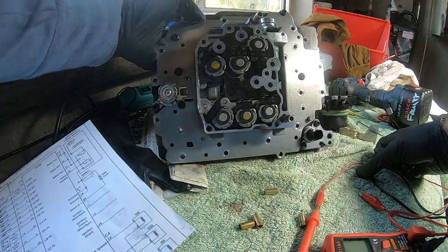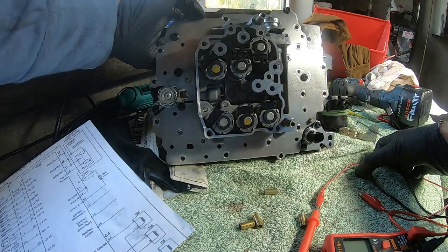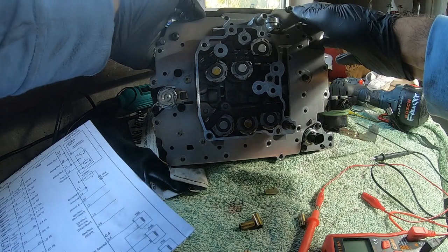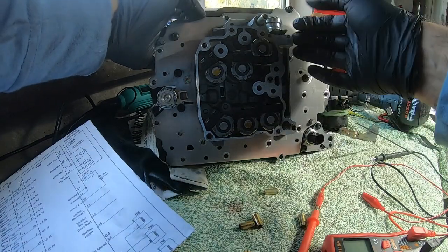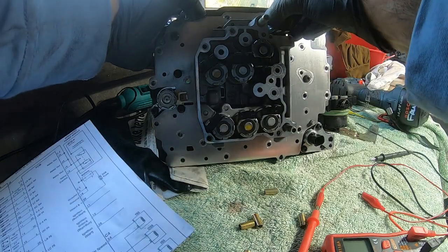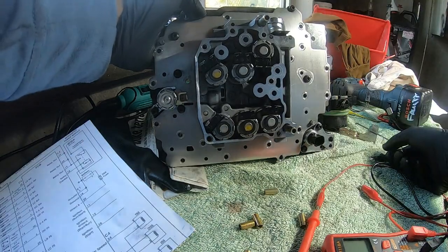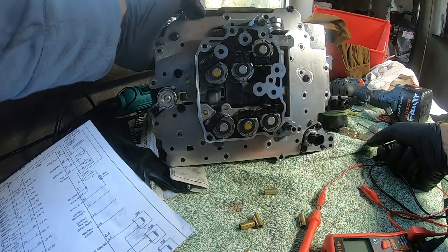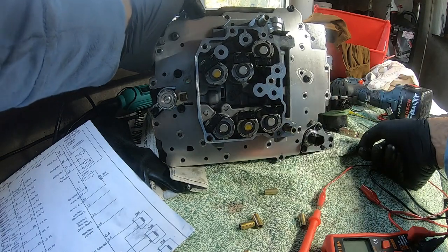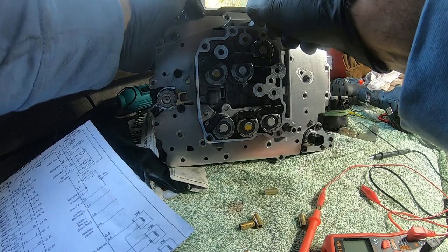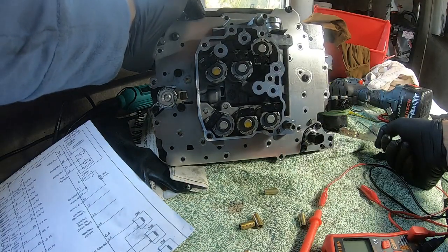You can take them out, clean them, measure their resistance, and then put them back. To take this one out, you'll have to take out the whole valve body, remove this whole setup, and at the back there are these 2 pins which are holding it down. You have to push these pins out, and only after that it will come out. I usually never have any problem with this one, and the reason I'm working with the transmission, it does not have anything to do with whatever I'm doing right now. So I'll just ignore it because it was working fine already. These 2 dowels are permanently mounted onto this housing. You never need to take them off.